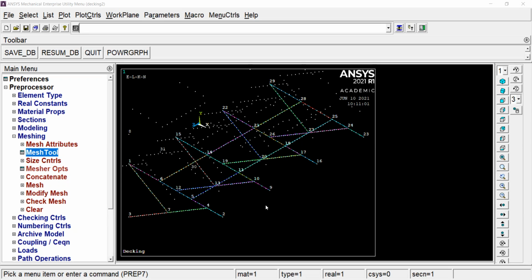So we will break our plate according to the key points that are set up, the grid. This is a grid now. So a 3x4 grid. So I'll create one plate here, one plate here, one plate here, here, 12 plates, which will all be connected to each other at these different key points, or these different nodes. So it'll act like a single plate that is being supported by all this structure underneath.